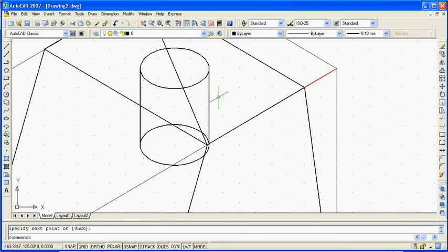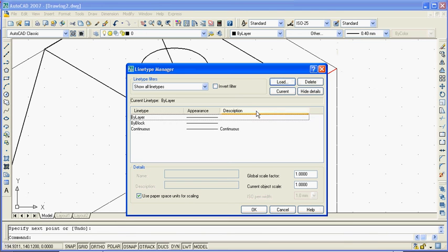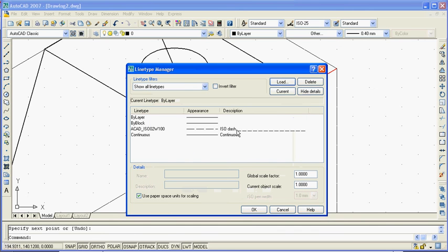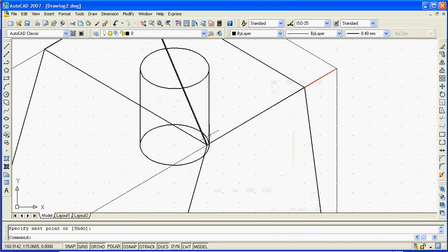So now these lines, even a continuous line, will not be visible inside the object. So we have to convert this line into a dashed line. Go to line type, other, load other line types. Okay, you can say dash dash. Select dash dash. Say okay. So this dashed line I can use. Say okay. So select these three objects.